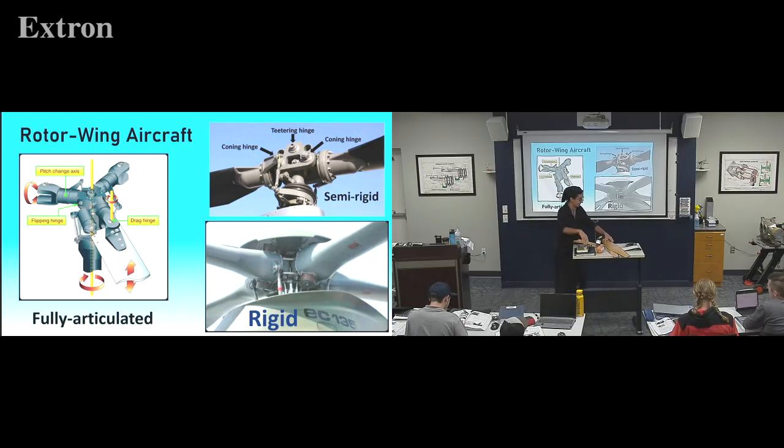I believe it's like the rotor tip-back plane. It changes your whole rotor head instead of leaning forward. So that, the PC link with the red tape on it, the rigid, that's a PC link. It'll literally change the pitch of your blades, and the whole head has a cylinder on the bottom that actually pivots like this inside the helicopter.